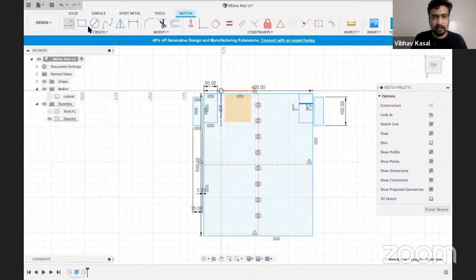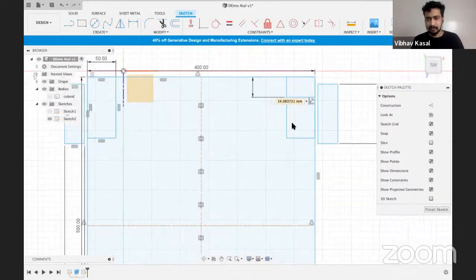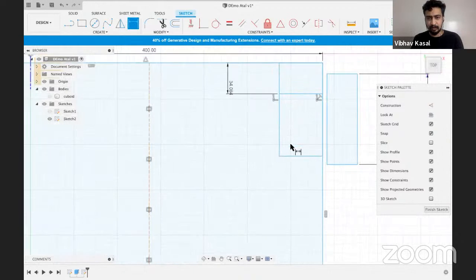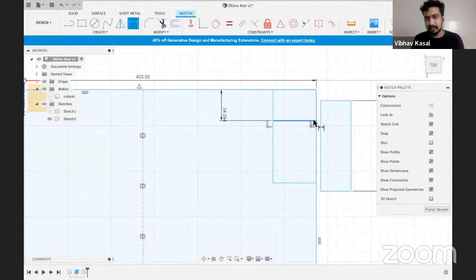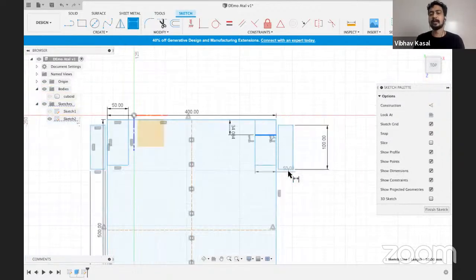And you also have to define the shaft with respect to the motor's length. Okay, you define this. So now I know the shaft will always be here with respect to this edge of the motor. Then if I use this and align the midpoint of this, then if I change it, the wheel would not have been changing the dimension.